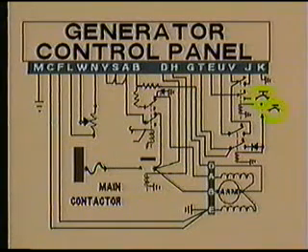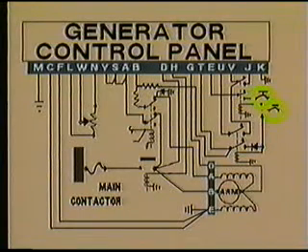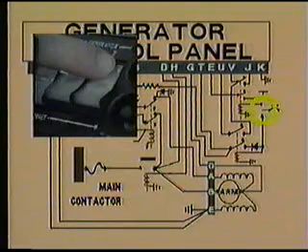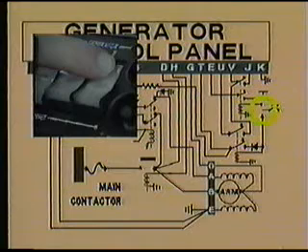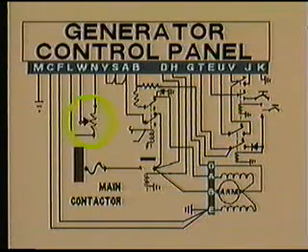Also included in the circuit are several circuit breakers that protect various parts of the circuit. The generator on/off reset switch located in the cockpit switch panel. A variable resistor that allows us to adjust the output voltage of the generator, and two limiting resistors.